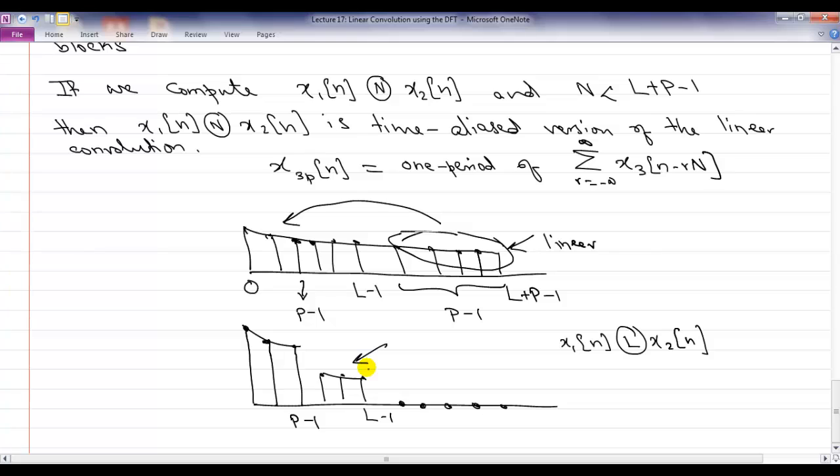It basically takes your signal and does circular convolution instead of linear convolution. Now if you do circular convolution, your first few samples will be corrupted. So it throws away those samples and keeps the remaining L minus P minus 1 samples. Now for the corrupted samples, it has to redo the circular convolution.